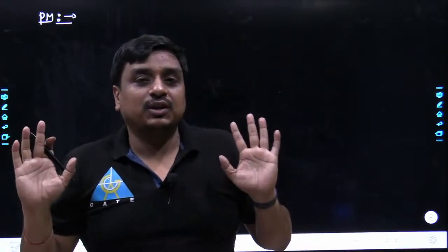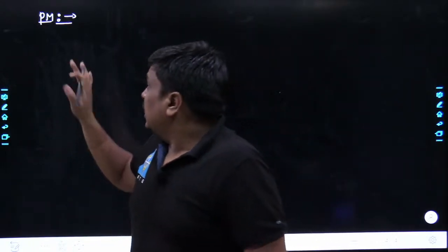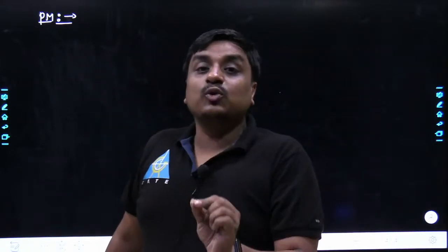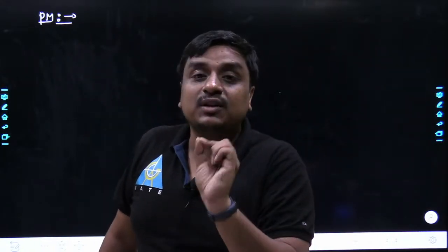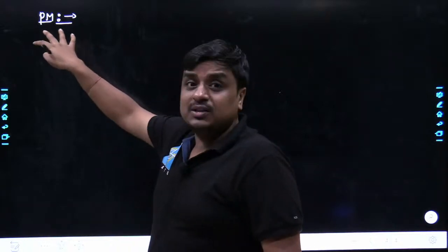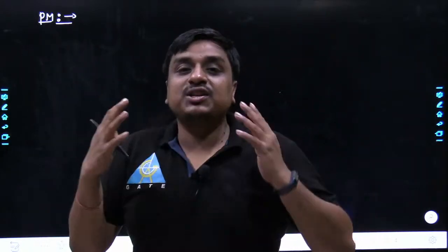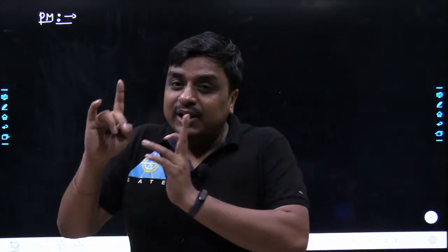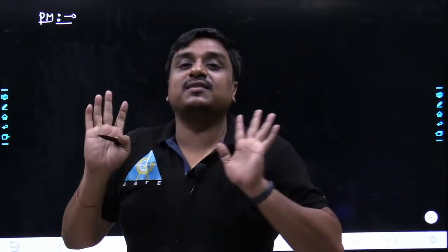Could you understand what I am saying? If a system is a stable system, I would like to know how stable that system is. That would be accounted for by the phase margin. If it has a higher margin in phase, that means I can introduce more and more phase lag into the system, and still the system is a stable system.